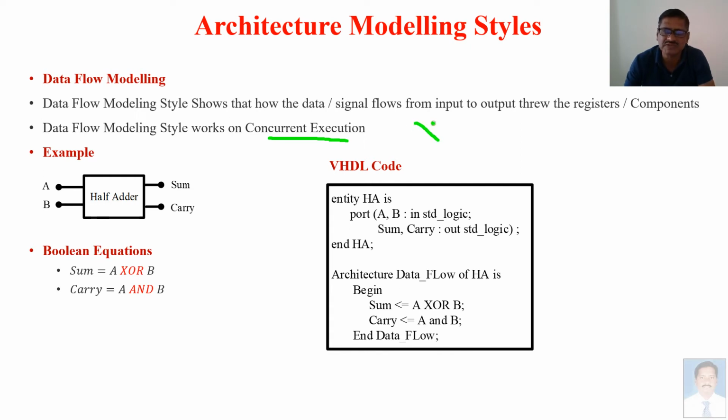No process is required for any modeling except the first one, that is behavioral. As well as in the mixed modeling style, if we are using the behavioral part, in that case again we have to use that process. Especially for data flow modeling style and structural modeling style, we don't require the process statement.